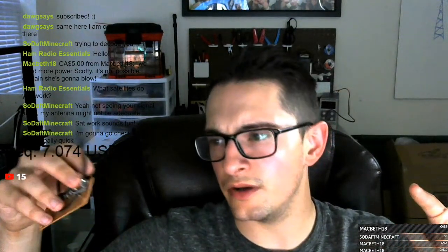That connects to an antenna feed line, and whenever radio waves hit your antenna, the magnetic field and electric field cause electrons in the antenna feed line to vibrate, and that causes a little bit of a voltage, just a small amount of voltage. Well, that travels down the line in between two capacitors here, and that's actually stored in the bigger electrolytic capacitors here on this board.